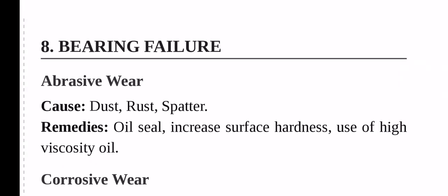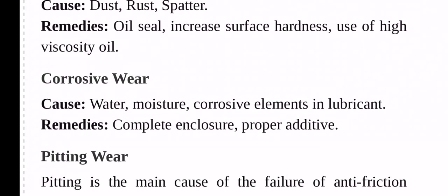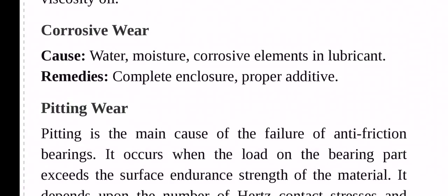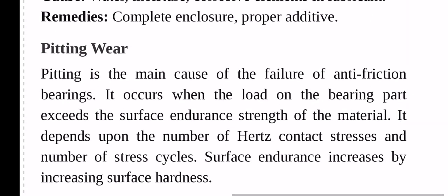Bearing failure. Abrasive wear: cause is dust, rust, spatter; remedy is oil seal, increased surface hardness, use of high viscosity oil. Corrosive wear: cause is water, moisture, corrosive elements in lubricant; remedies are complete enclosure and proper additive. Next, pitting wear.